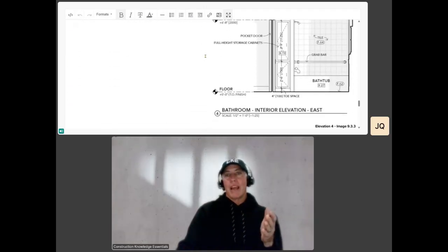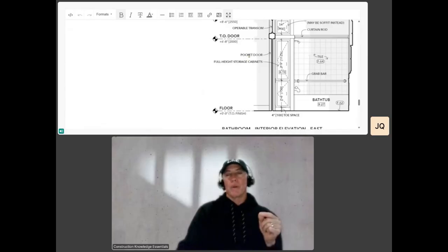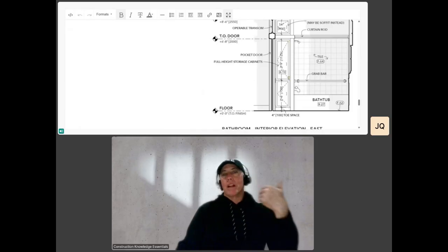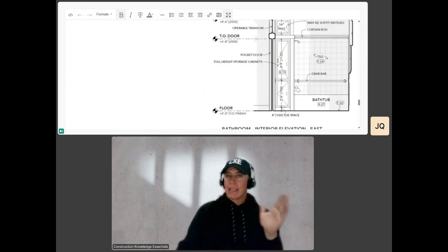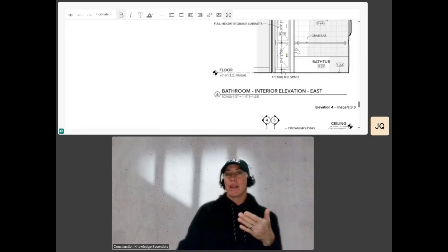We head down, and you can see the corner or the point of this is, in essence, the opening side, or the hinge side, I should say. That triangle being built is basically saying this top to this bottom says we open on that side and we stay tight to the wall or the millwork on this side. So the door opens and you can actually see the handle right there. So it opens, swings that way. Same with the bottom one.